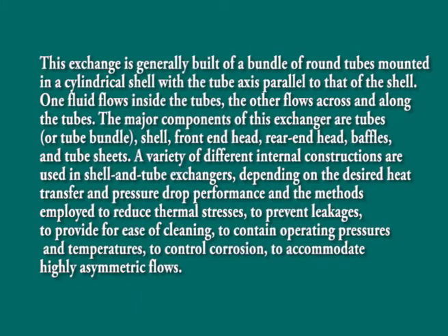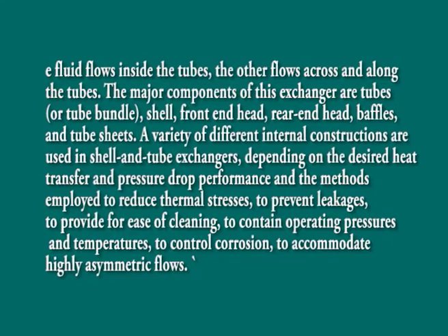to provide for ease of cleaning, to contain operating pressures and temperatures, to control corrosion, and to accommodate highly asymmetric flows. Shell and tube heat exchangers contain a large number of tubes, sometimes several hundred, packed in a shell with their axis parallel to that of the shell. Baffles are commonly placed in the shell to force the shell side fluid to flow across the shell to enhance the heat transfer and maintain uniform spacing between the tubes.